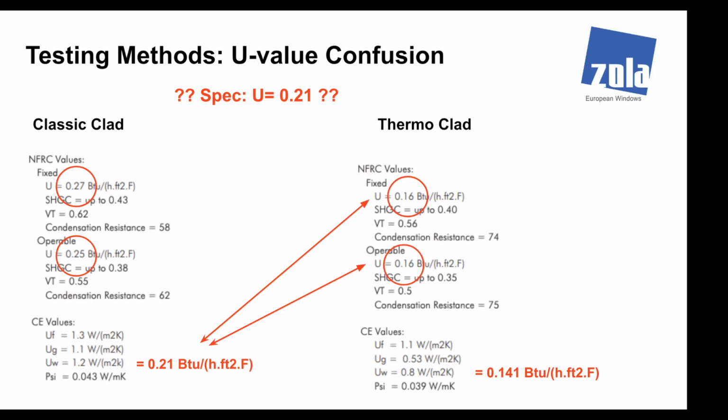Since we were talking about all of this with the different glazings and the fact that you don't have Krypton, my question was, have you guys been looking at vacuum insulated glazing? It has to do with longevity, price, and we would have to change our frames to accommodate the thinner glass.